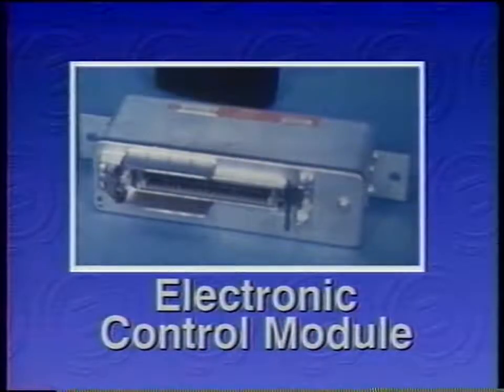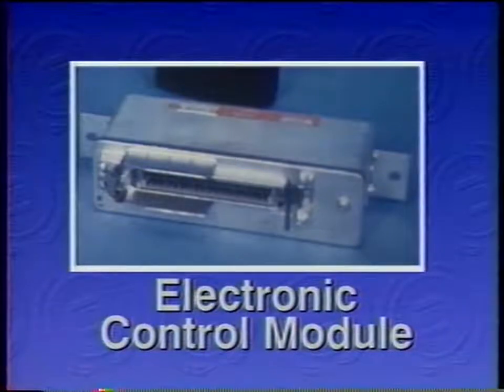The Bosch 3 electronic control module is configured for 4-channel operation rather than 3 as with Bosch 2 units. Location of units varies by application. Since some applications have identical connectors, care must be taken that the right module for the application is being used.